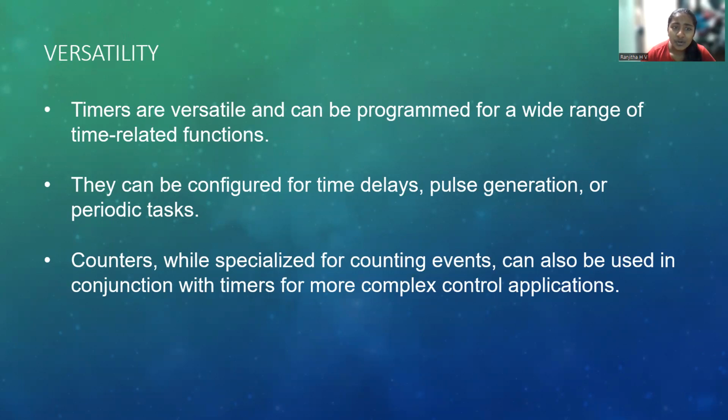Versatility. Timers are versatile and can be programmed for a wide range of time-related functions. They can be configured for time delays, pulse generation, or periodic tasks. Counters, while specialized for counting events, can also be used in conjunction with timers for more complex control applications.